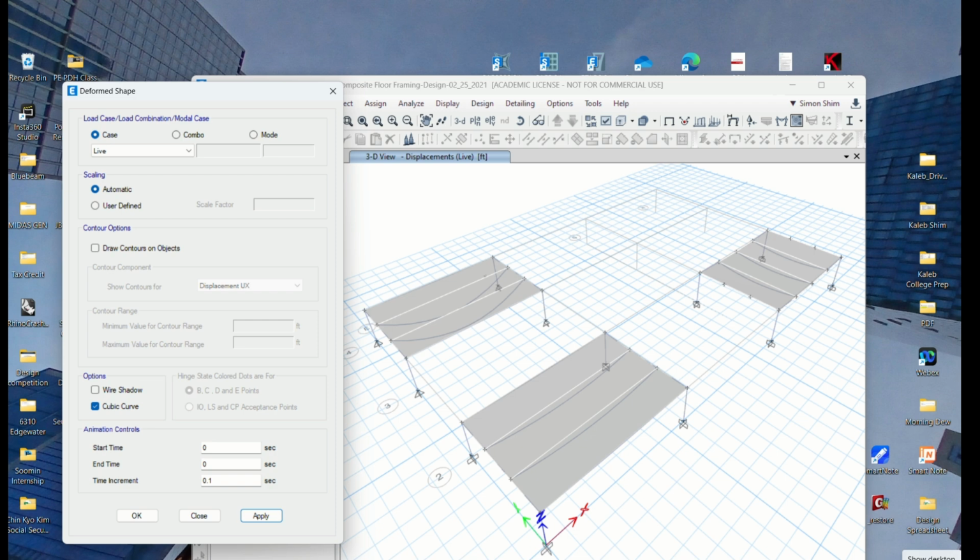Because composite design is more like a beam design module, not an analysis module. And in the frame modeling here, they don't have any kind of input for such things. ETABS recognizes this slab and beam as tied together, but it is more of an independent situation. They do the load transfer, but basically they do not understand composite action here. Only the composite beam design module does.